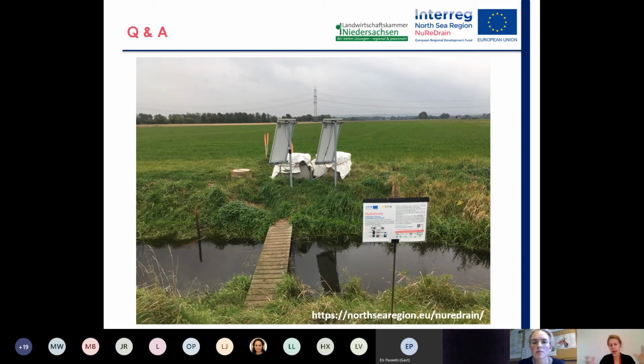I mean, like just the size of the filter? Like you said, the pre-filter. Yes, okay. So the diameter of the P filter itself is 1 meter. So 1 meter concrete elements. And the filter dimension is 40 centimeters filling height of the material. And over a distance of 1 meter it needs to be flown through by the drainage water before it discharges into the drainage tile and then into the surface water.